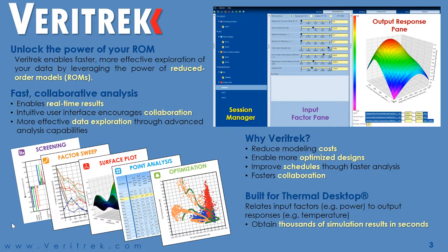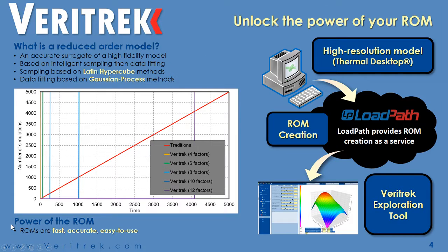Again, I just want to reiterate that this is a tool currently built for thermal desktop. It relates input factors such as power, thermal conductivity, or optical properties such as emissivity to output responses such as temperature or hydraulic power. And finally, just to reemphasize, we can obtain thousands of simulation results in just a few seconds.